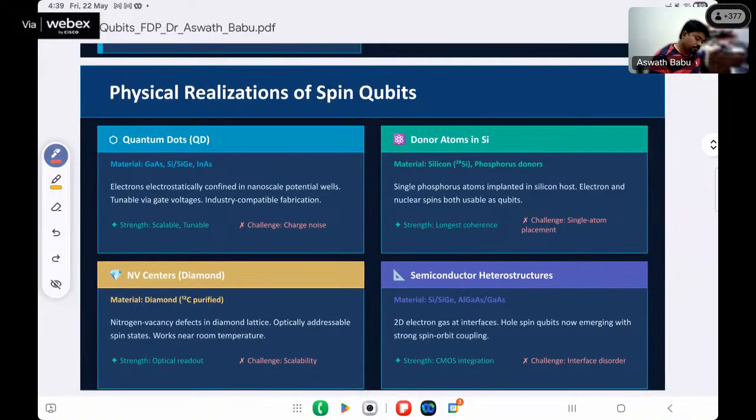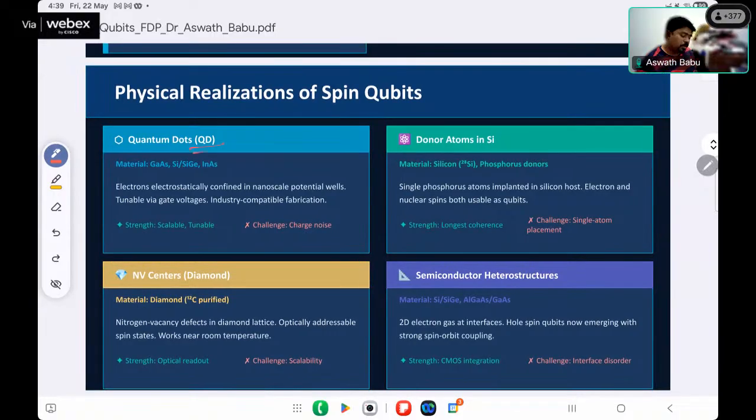Yeah. So that is a quantum dot inside a semiconductor material. Okay, so how is it done? We take some donors like pentavalent phosphorus donors and dope them; pentavalent means extra electrons. Usually silicon requires 4 valence electrons to share and create a bond, but we give 5 using phosphorus donors. In this way, one extra electron is lingering around in the material. We can make that electron locate at some fixed location.